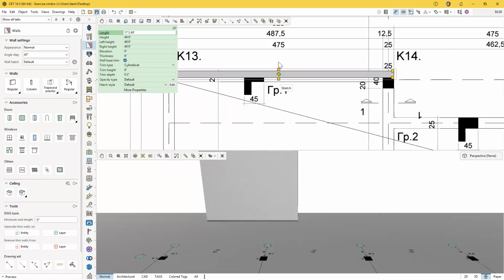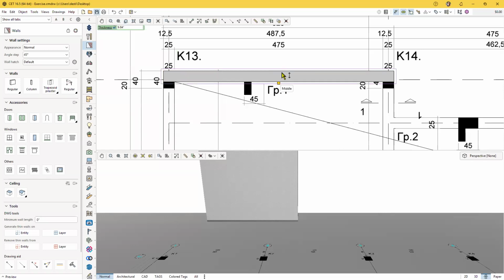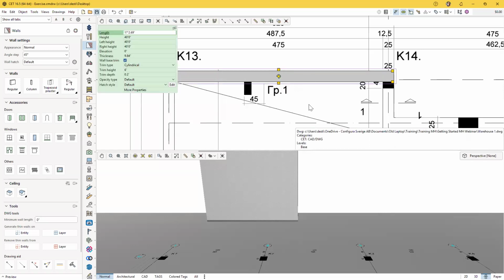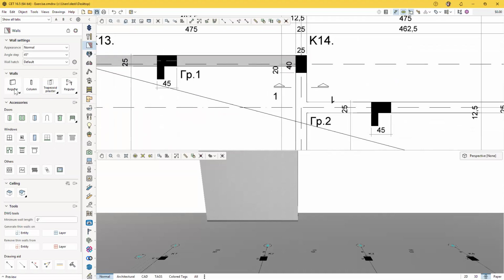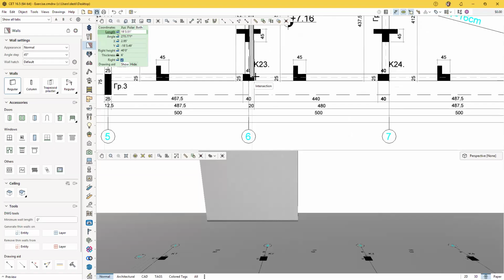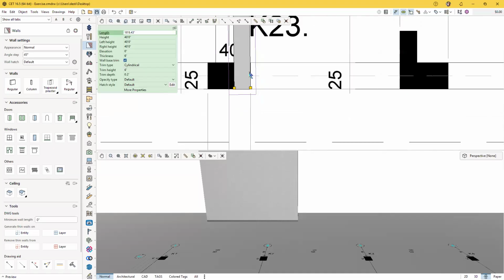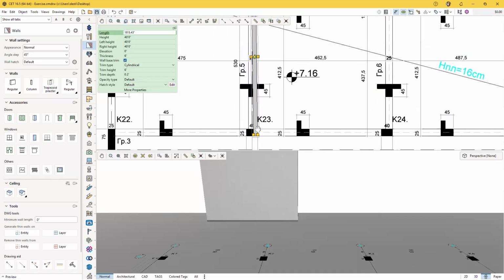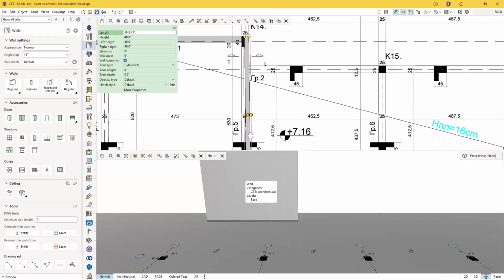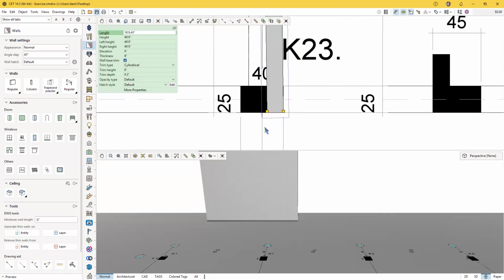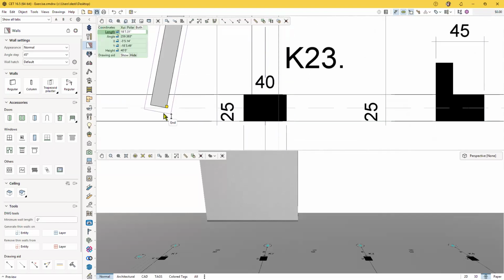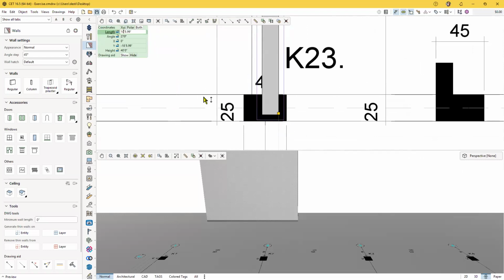All right. Now let's talk about these stretch nodes. Let's say that I want to make this wall just a little bit thicker. It will snap to that line for me. So it makes it nice and easy to add these all together. Now I can, again, choose where I want to start all of these walls. Maybe I want it to be this exterior side. And if things are misplaced, so I can see that this wall is kind of not really in the right place here. I've got some things kind of moving around. I can actually just grab those stretch nodes and stretch it and snap it wherever I need it to be.